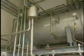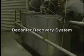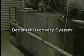Decreased regeneration frequency and time can reduce the capacity of the carbon bed, leading to breakthrough. If information is available, the quantity of recovered organic material should be compared to baseline values. If the quantity of organic vapor entering the adsorber is constant, a reduction in the amount recovered indicates reduced collection efficiency.